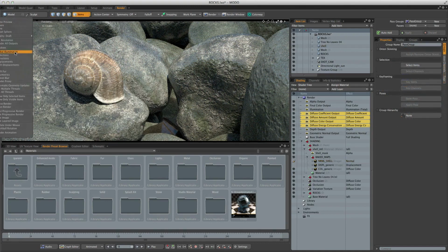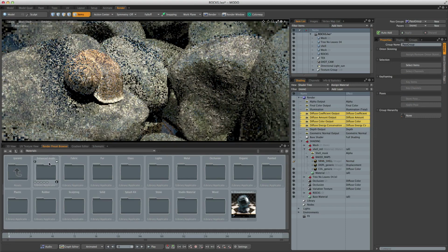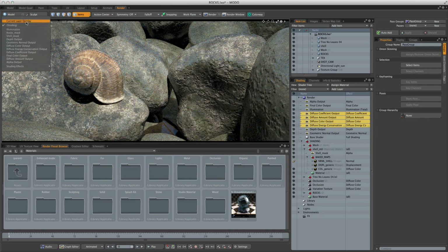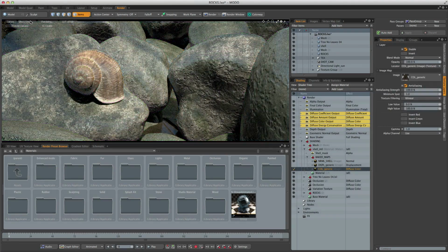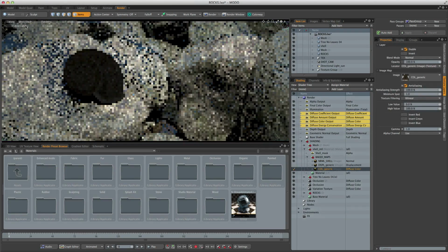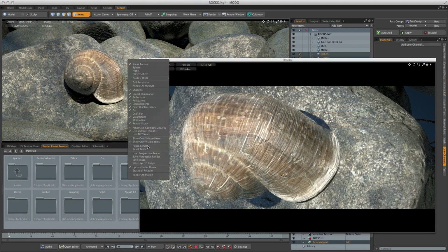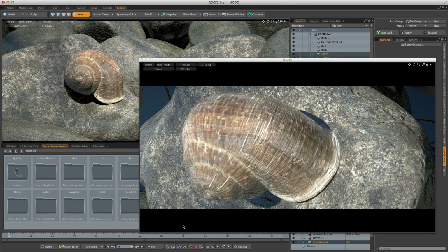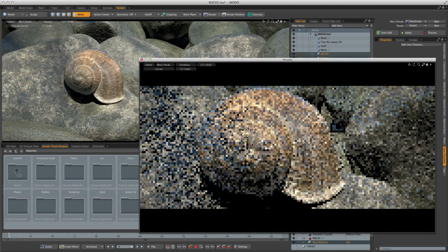It also allows you to strip the scene apart without affecting the actual scene itself, by hiding certain things from the renderer. You can also preview any outputs that are in the shader tree, and it also allows you to isolate individual shading layers to see how they're affecting the image. It can also be used as a renderer in its own right, as you can save directly from it, and you can have as many previews open as you need at any particular time. Its importance in the development of a scene cannot be overstated. Fast feedback means faster decisions, which means it speeds up everything you do.